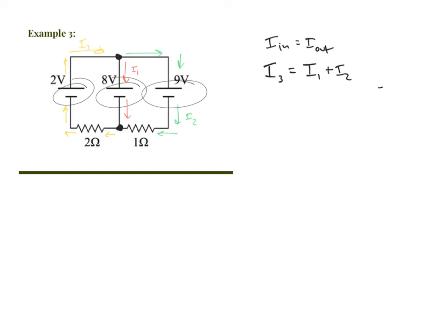So we're going to take each side of the circuit and evaluate it as a loop. I like to go clockwise. You can go whichever direction you'd like, but I like to go clockwise. And you choose arbitrarily a point to start at. I'm going to start at the positive terminal of the left side battery on the left side loop, and I'm going to evaluate the left side loop. I go around that loop clockwise, like my little swirly thing indicates, because I picked that direction.